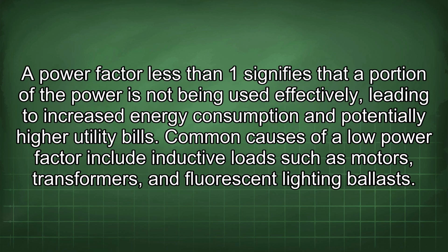work. A power factor less than 1 signifies that a portion of the power is not being used effectively, leading to increased energy consumption and potentially higher utility bills. Common causes of a low power factor include inductive loads such as motors, transformers, and fluorescent lighting ballasts.